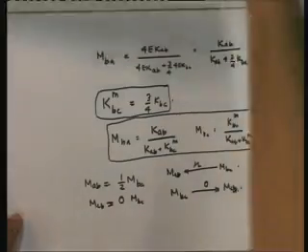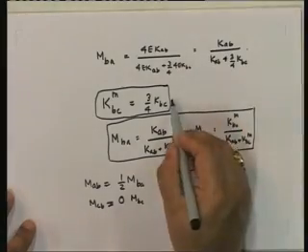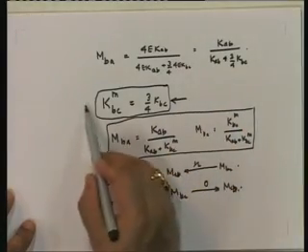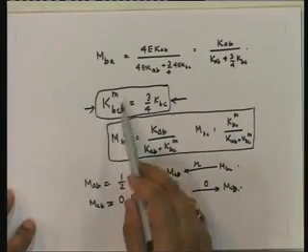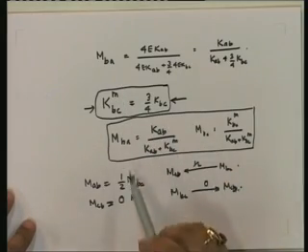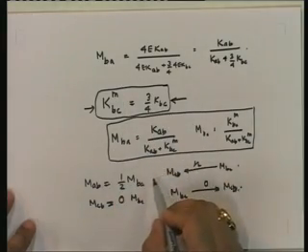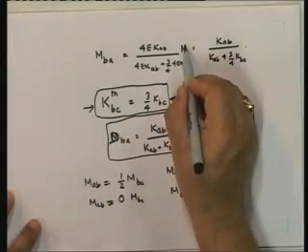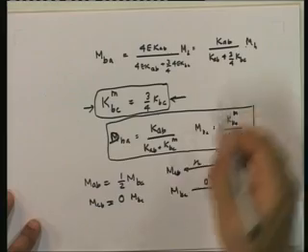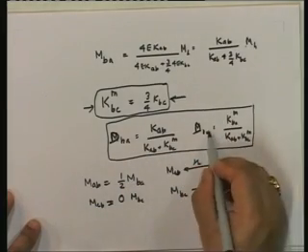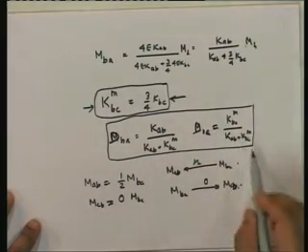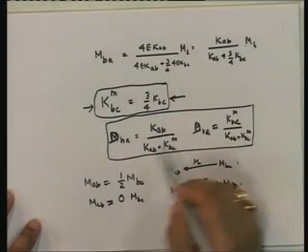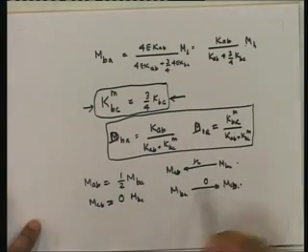However, for the modified member, the stiffness is modified to 3/4, and the distribution factors are computed accordingly. So if we modify it, then we can continue using the same, and the only other thing is that in a modified member there is no carryover.